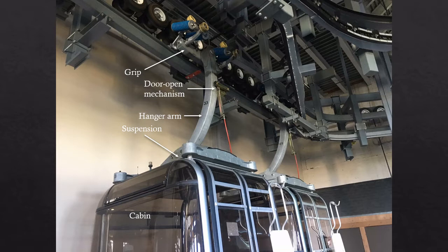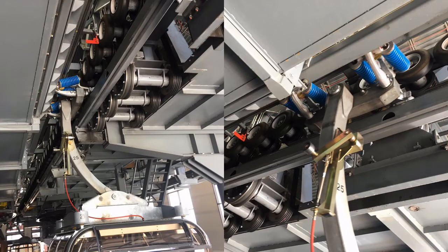Lastly, the door open mechanism opens and shuts the doors in the terminals and ensures that the doors are fully locked. These are close-up images of that door open mechanism. Both are shown in the door locked position. As the cabin approaches the point in the terminal where it is to unload, a metal rail will push this roller upwards, and now we'll unlock the door. When it's time to close, this rail, another rail with the opposite shape as one can imagine, will push the roller back down to this position, and the door will be locked.